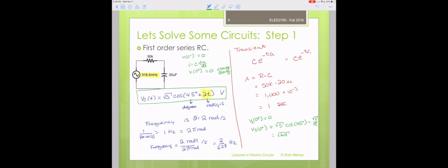And of course, if we're going to go through the rest of this, we realize that Kirchhoff's voltage law has to hold. So the voltage on the resistor simply has to match whatever's left in the circuit. So in our circuit, we have Vs is equal to VR plus Vc, which means that VR is equal to Vs minus Vc.